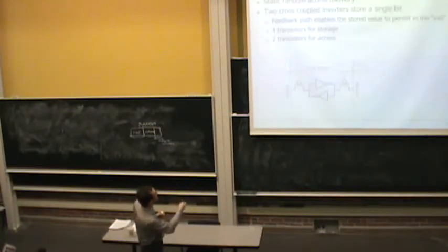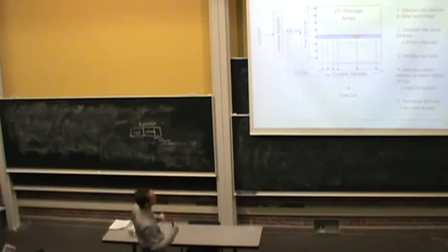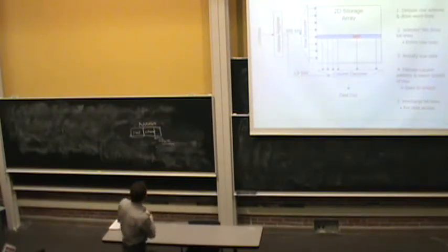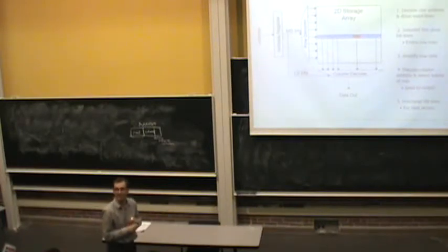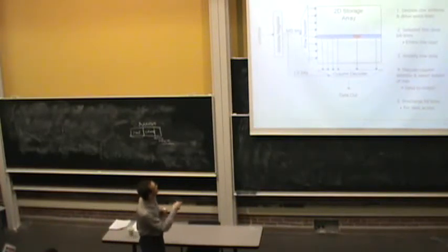All of them drive their bit lines down into, well, these are the bit lines shown here, into the column decoder. And the column decoder's job is essentially to use the column bits to select which column should be read out of the memory. Make sense? So the operation is very simple. First, you decode the row address and drive the word lines, or row select lines.